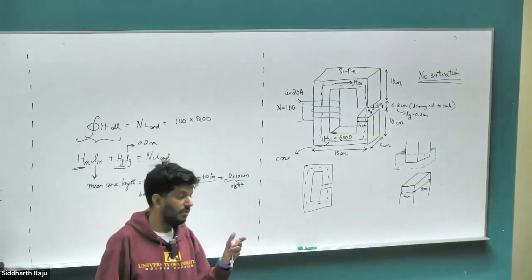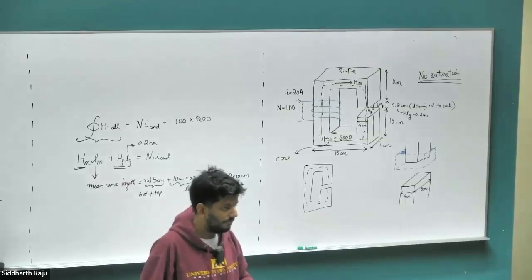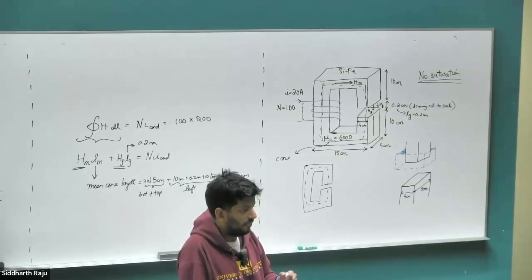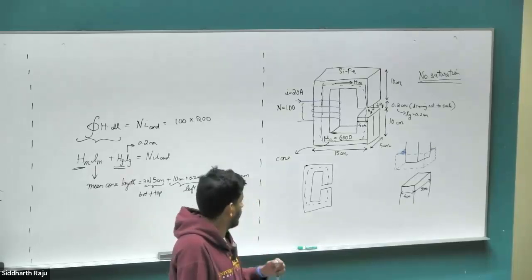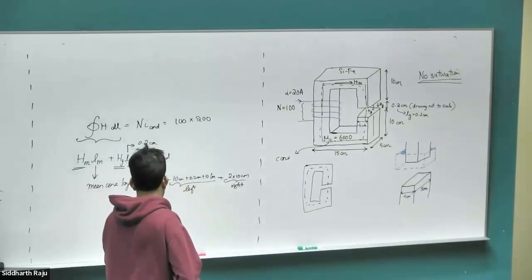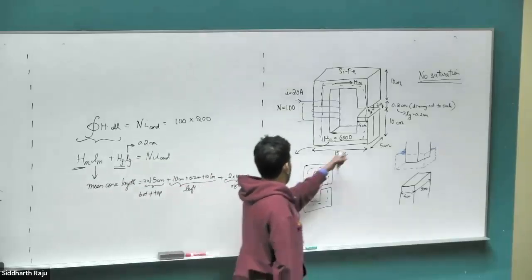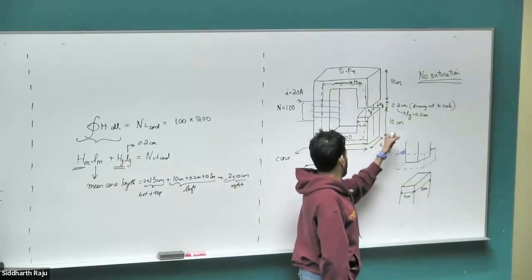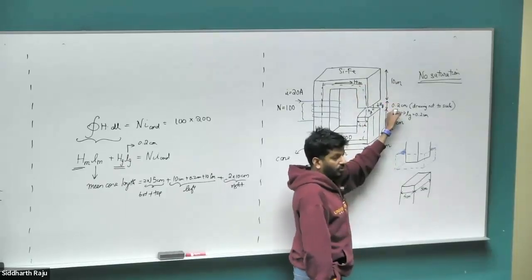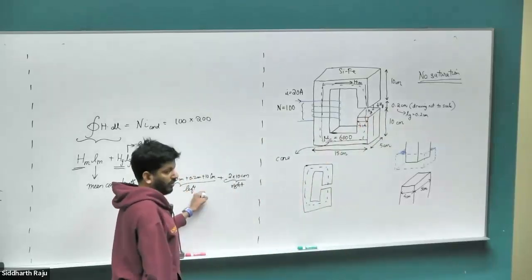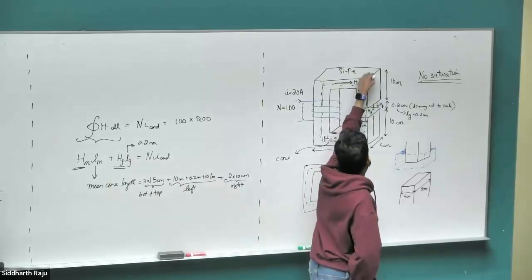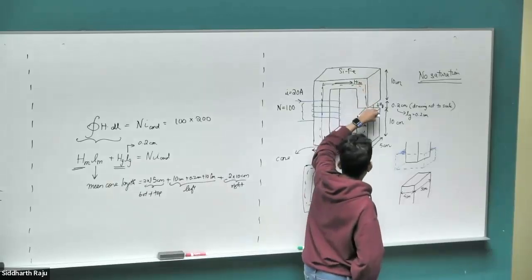I have a question. On the left, you don't have the air gap, so that's 2 times 10, but on the right, the air gap adds length. Would they not be the same? Oh yeah, so here, the left hand side length is exactly the same as the right hand side length. So 10 plus 10 plus 0.2. On the LHS, that's what I have here. When we come to this side though, the iron core is only this 10 centimeter and this 10 centimeter.